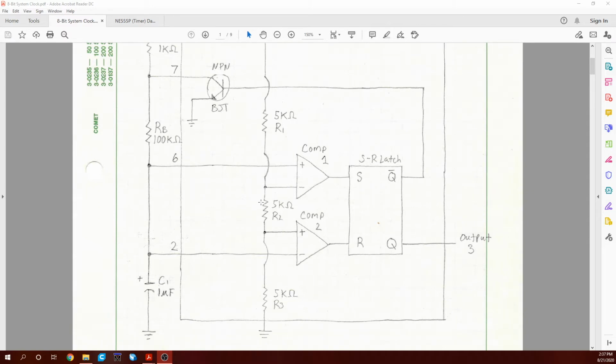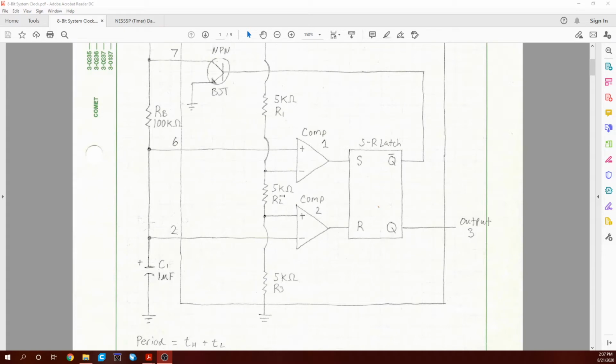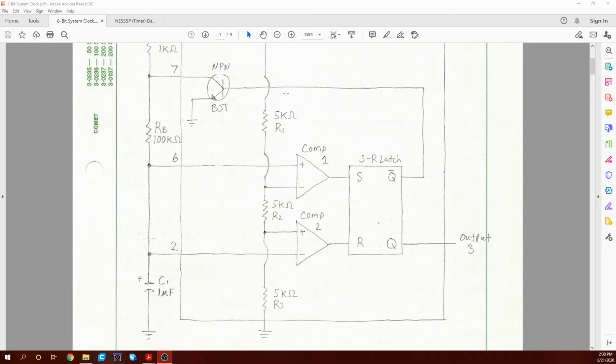So what's happening here is we have a couple comparators, and basically what they look at is, hey, we got positive voltage coming in and a negative voltage. If one is higher over the other, it activates and lets a signal out. And if the signal comes out, it goes through this SR latch, and we will talk about digital logic here soon. So don't worry about this today. Just know that it goes through a couple comparators, goes through a latch, comes into this transistor up here.